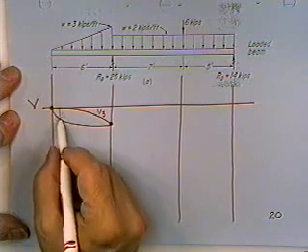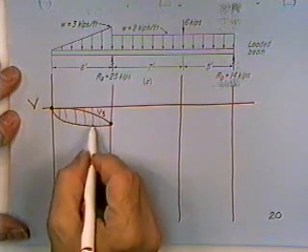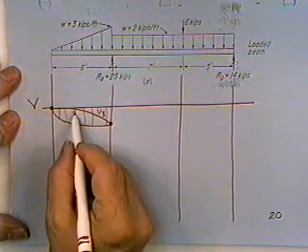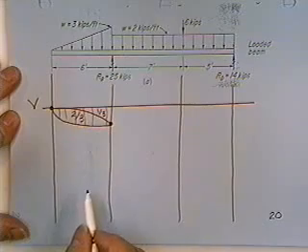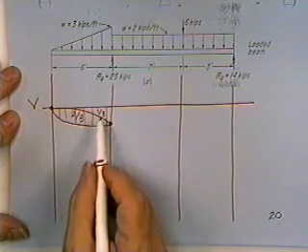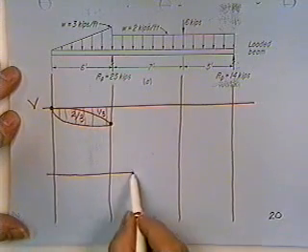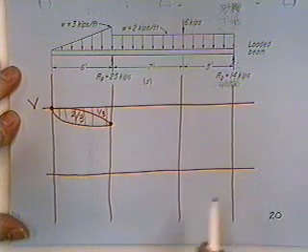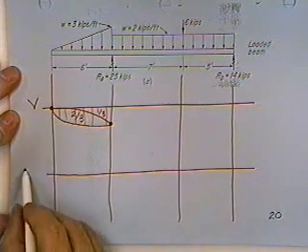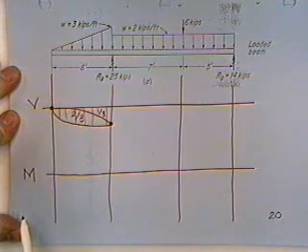Turns out if it's this fat curve, then the area under the fat curve would instead be 2/3 the base times the height. So it really is important I know which one, because on this next moment diagram, that's going to throw the point off if I don't get the right curve.